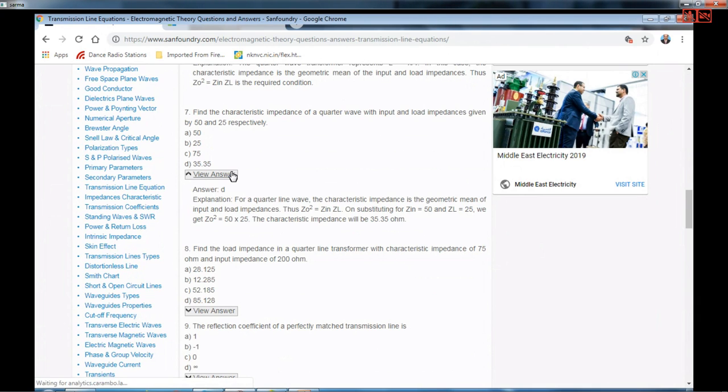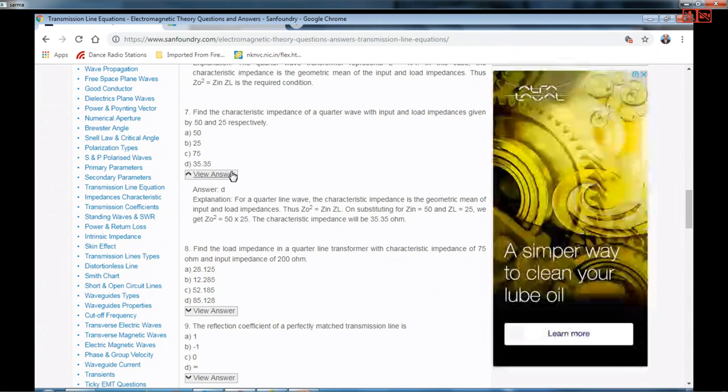Suppose we reverse it. It works on the same lines. That is, a 50 ohm load appears like a 25 ohm load to the source impedance also. So it can be used either way. Please remember, it's not that it converts only 25 ohms to 50 ohms. It can convert 50 ohms to 25 ohms also, because a transmission line is basically a symmetric circuit or network.